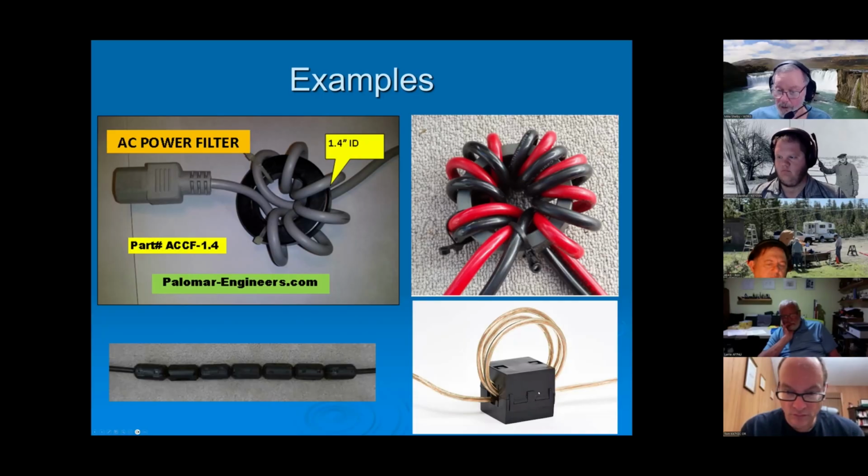Over here in the lower right-hand corner, that's very typical of what you do. USB cables are kind of a number one nemesis as far as getting the RF into it, and it really screws up your radio and screws up your PC that you're talking to it. So you just don't grab one of those clamp-ons and run your USB cable through there one time. You want to get as many loops in there as you possibly can to knock it off.